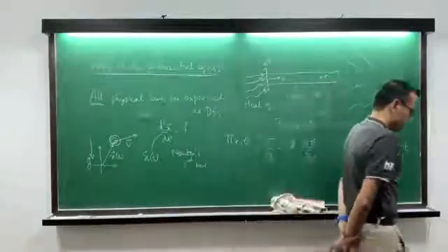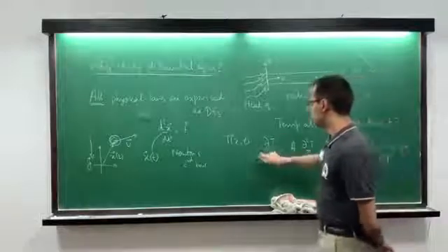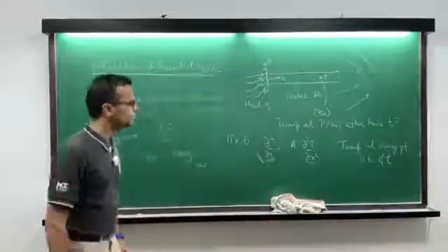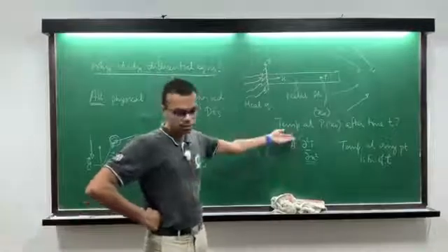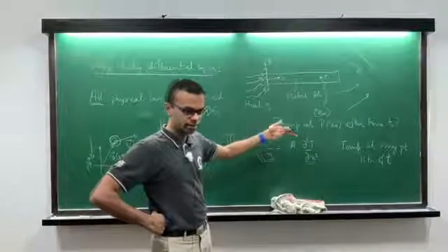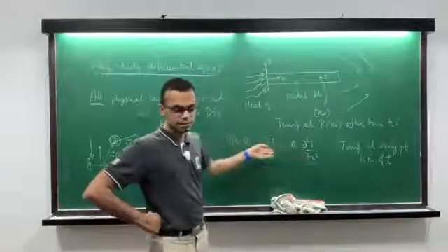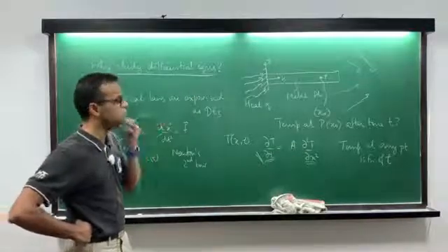Okay, and this is a standard diffusion equation if you have seen it before, a 1D diffusion equation in two variables, a partial differential equation, and it's still a result of a physical law. Okay, there are two physical laws that are here. There is one that is energy balance, that's what gives you the left hand side, m c_p dT by dt, if you have seen that before.